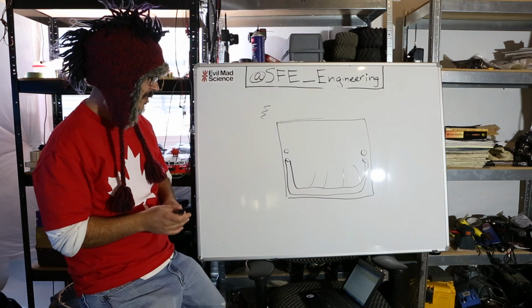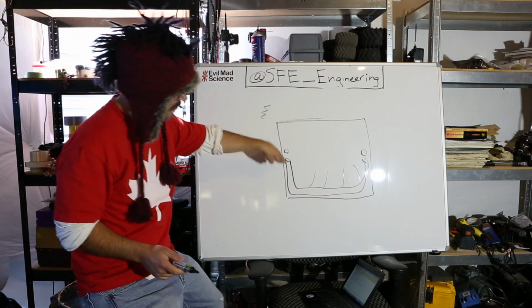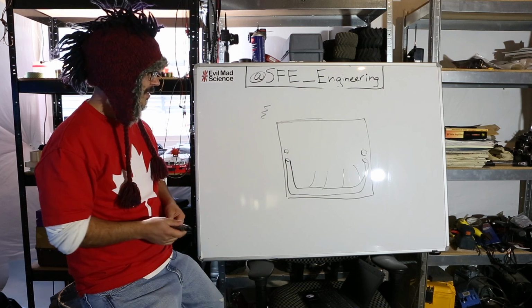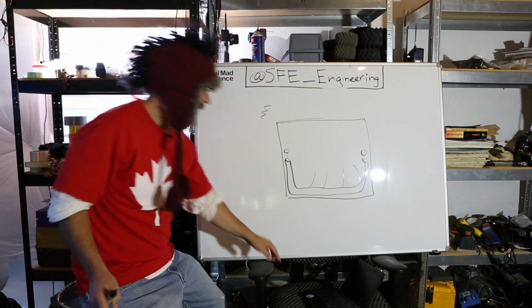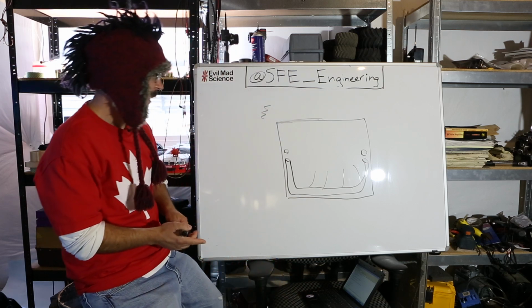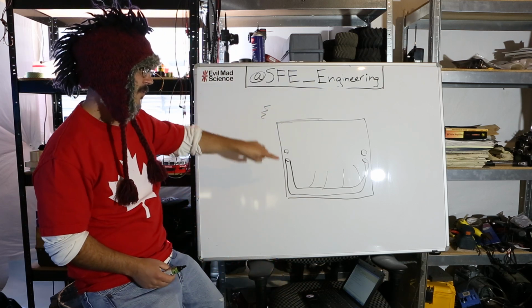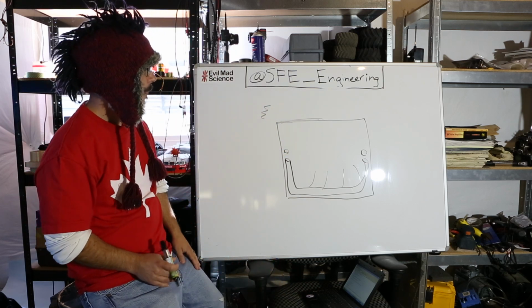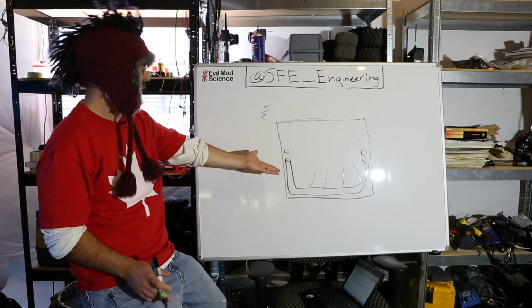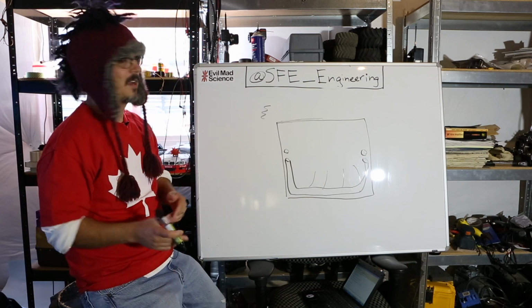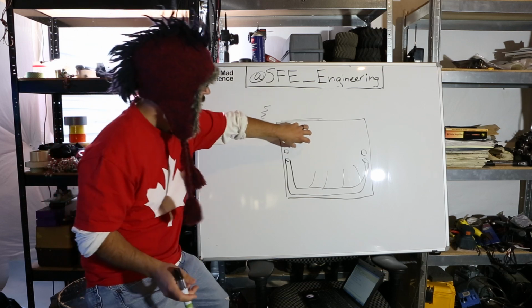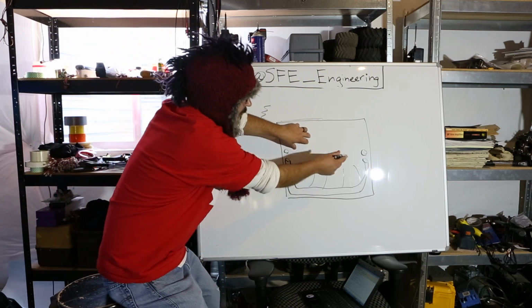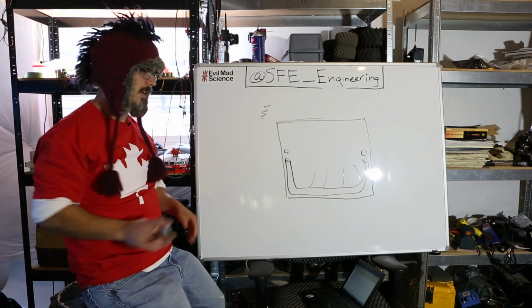My other gut reaction to this is anytime you do something like this, you're basically making an antenna, right? It's either transmitting or receiving. So you can really expect to have some difficulty when you're doing that sort of thing. If you're not daisy chaining your design, I would not do anything like this. I would do it more the way I suggested the last time, which is a centralized power and a star configuration for feeding your power.